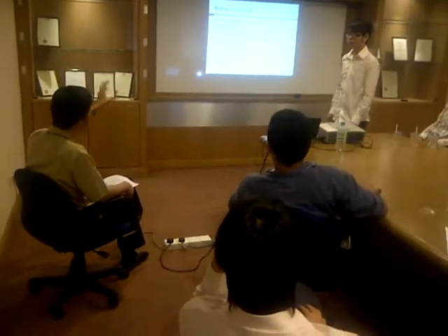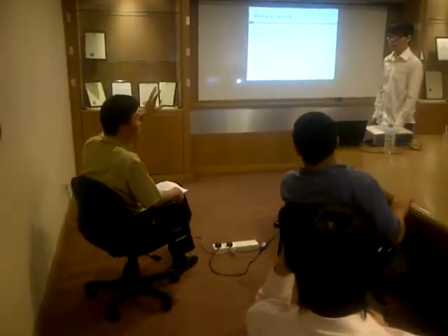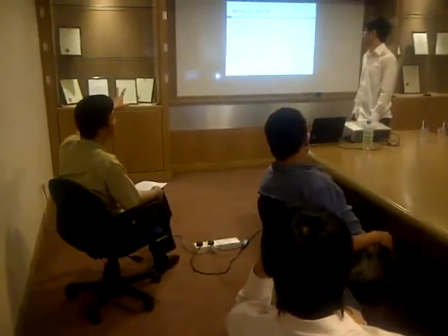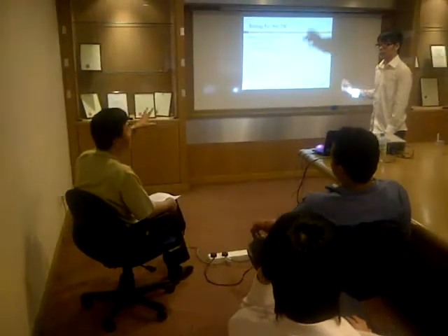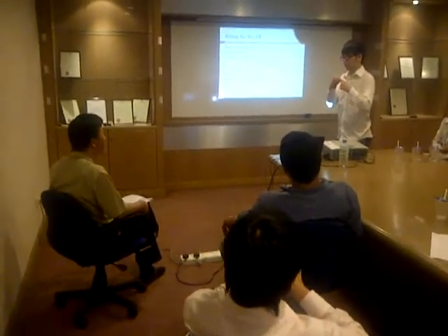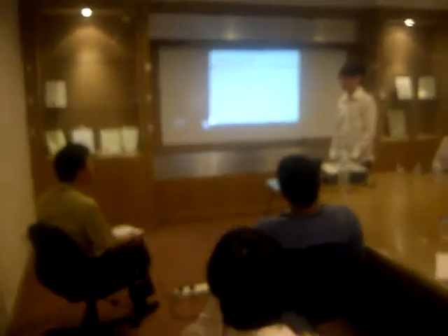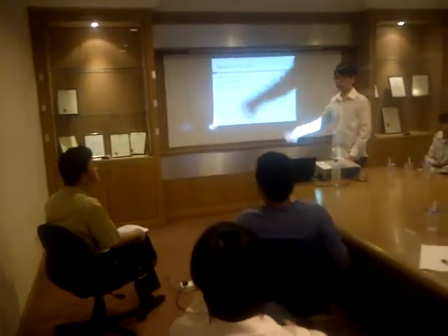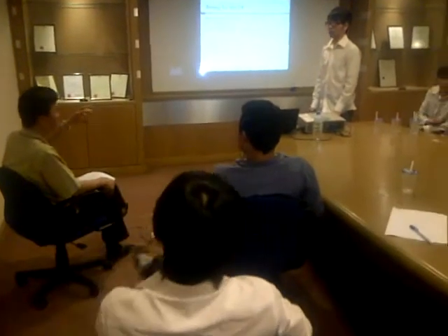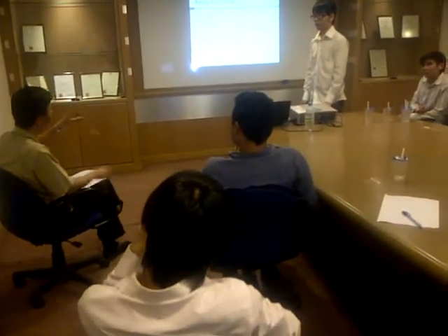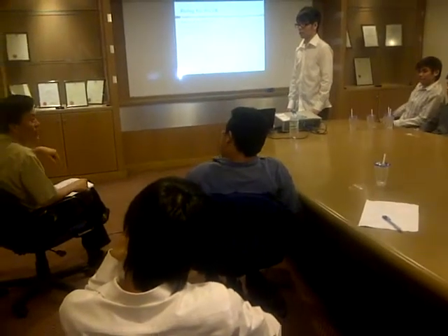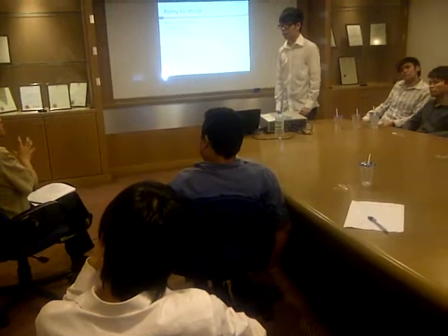So make changes. In our normal design, we assume one socket outlet is 250 watt. That is already enough, and we have designed so many, and never had a problem. So 500 watt cannot be right. But in their design, maybe one circuit switch socket outlet has a plug connected out again, or an extension, maybe extension 4 or 5. Even though 4 or 5, when we design 250 watt, it does not mean this socket cannot produce more than 250 watt. 250 watt is a good estimation.